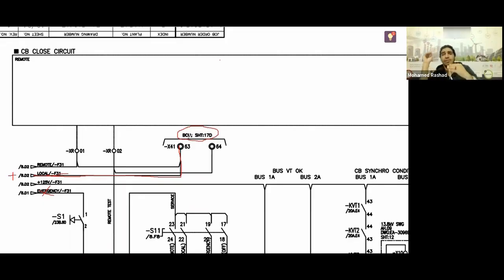So instead of bringing cables from the LCC or GIS room to this control room, which would cost me money, and a control room means space, which would also cost me money, and equipment and panels would cost me money, I will bring just one relay and install it in the LCC panel. The statuses, alarms, readings, and everything will be sent to this PCU. The PCU will be installed with me in the same panel, so the wires obviously won't exceed a few meters.